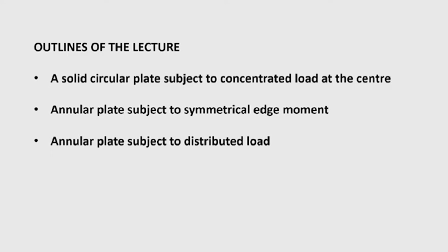In some cases you will find that boundary conditions have to be satisfied in the inner region as well as the outer region, especially in the case of the annular plate, or in some cases, especially for the concentrated load that I have given in the first item, you will find that discontinuity arises at the point of application of the concentrated load in the expression of slope and curvature.